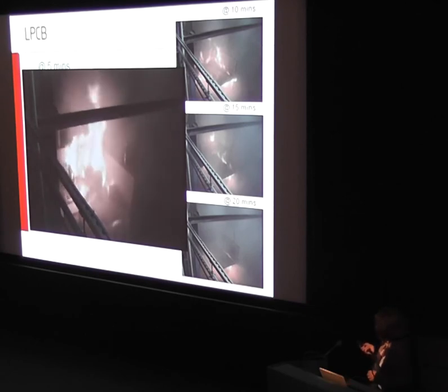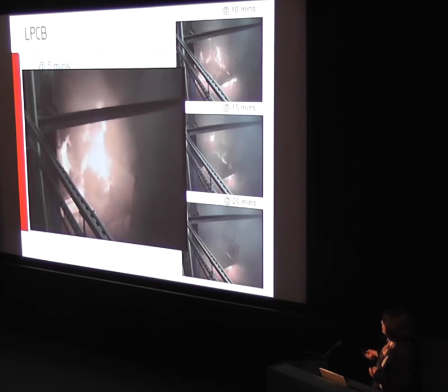I don't know how well you can see it here, but where we felt it was failing was it just didn't have enough momentum. There was water mist coming out from the ceiling, and a lot of it. Maybe we were unfortunate where we placed the fire load, but a lot of it you could see was just pushed the other side of the wall system of our fire load. So you could argue you're making the outside a fire-safe environment, and you really weren't affecting any control in the area of the fire.